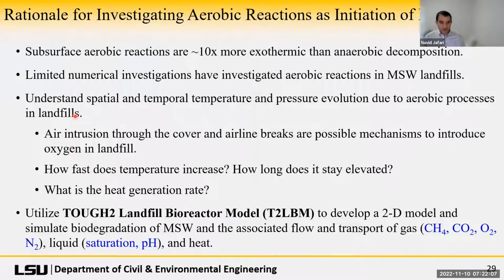And also we're going to use two different scenarios. We're going to use air intrusion through the cover. So that's the one that we always think about, but also one that, when we talk to the industry, is air line breaks as possible mechanisms to introduce oxygen and aerobic reactions. So what do we want to quantify? Well, how quickly does temperature increase? How long does it stay elevated? But more importantly, what is that heat generation rate? What is that number that then can help us down the line? To do this modeling, we're going to use the TOUGH2 framework from Lawrence Berkeley National Lab.